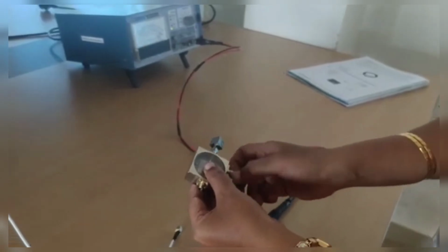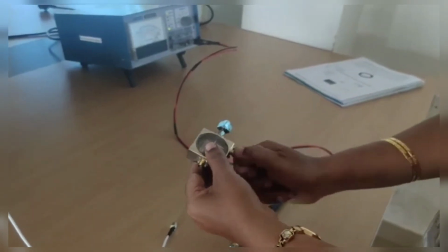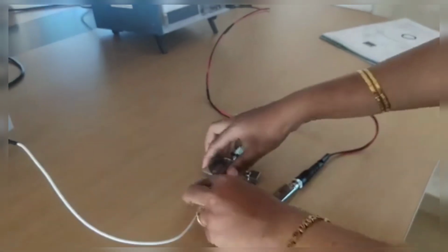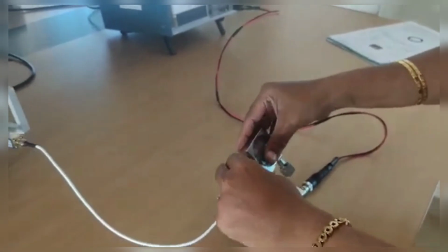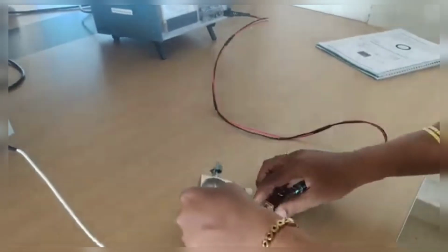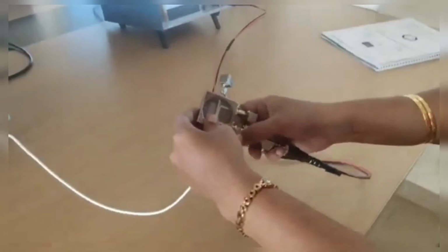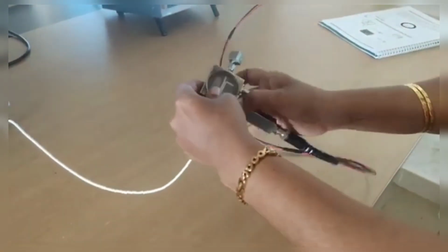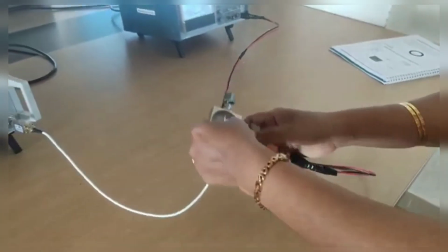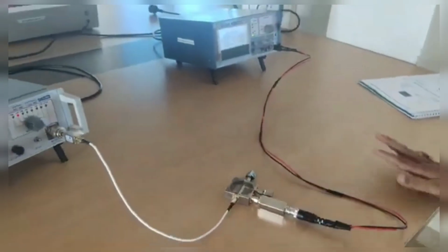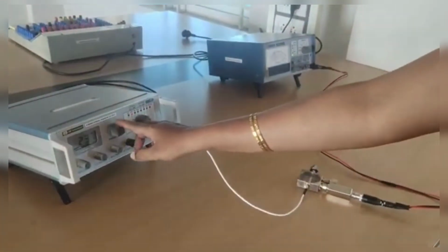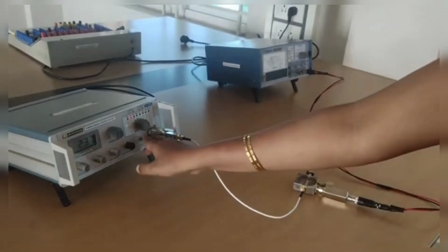Okay, and we can measure only the coupling characteristics, as we did in the ring resonator, the same way, and the connections have to be made using the detector also. So this detector is connected to port 3. This is how the connections are made using the detector, and once the connections are made like this, we can vary the frequency from 2 to 3 gigahertz and turn on the RF.